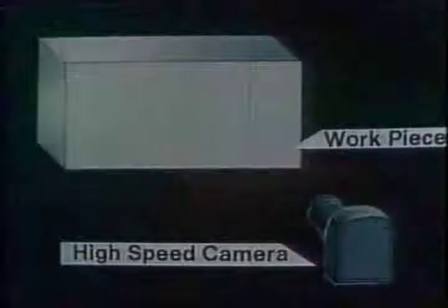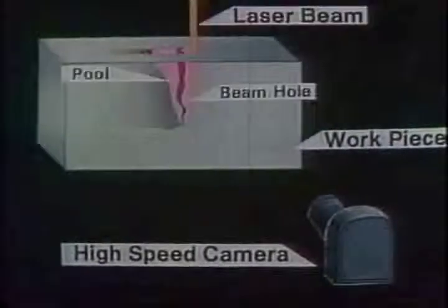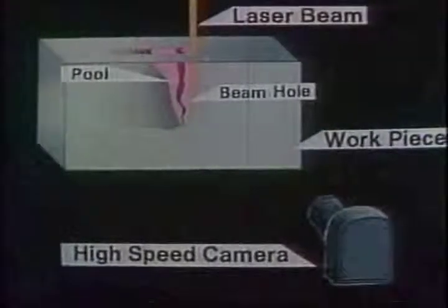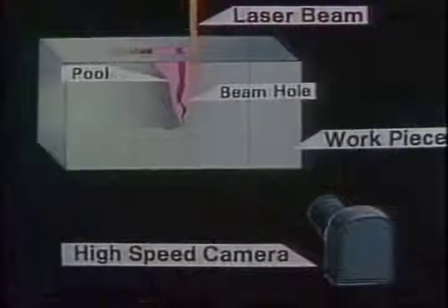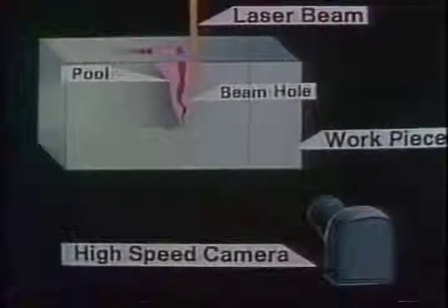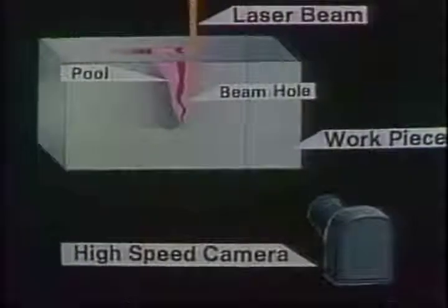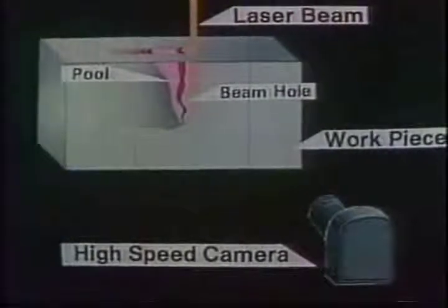Dynamic behavior during laser beam welding. Since the X-ray transmission method cannot provide high enough spatial and time resolution, laser welding of transparent glass was conducted to visualize the phenomena at 8,000 frames per second, which is a great deal higher than in the X-ray method. Due to its welding phenomena being similar to those of metal, soda lime glass was adopted here.